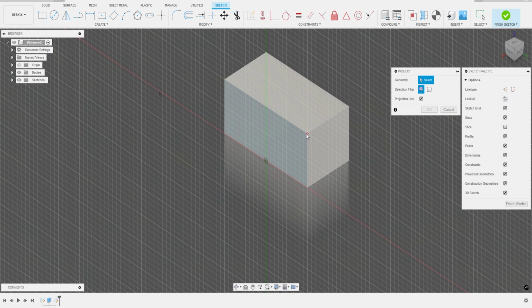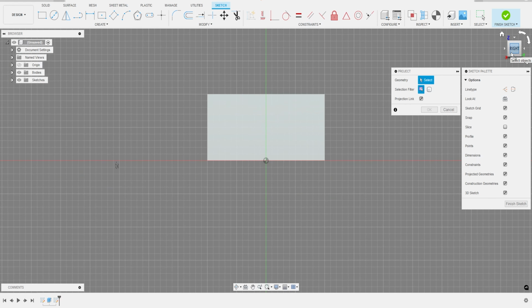By doing this, we make another tricky thing visible. We turned our object, so now we lost track of the 2D sketch plane. This means sketching becomes a bit weird. Not impossible, but in the beginning that can be confusing. So to come back to the 2D sketch plane, we can simply select the correct view we were in by using the rectangle icon and selecting the view.